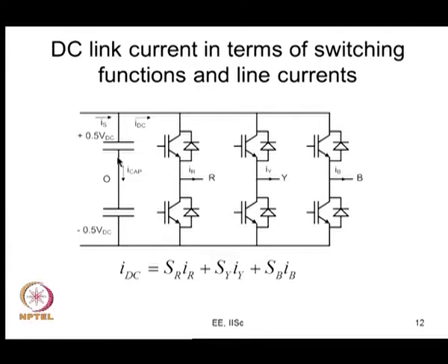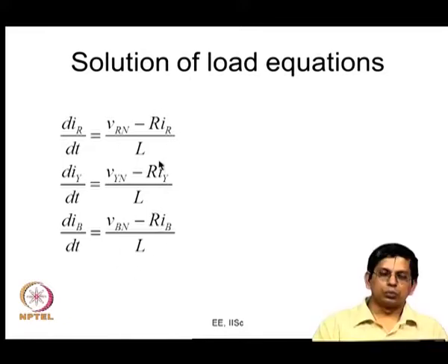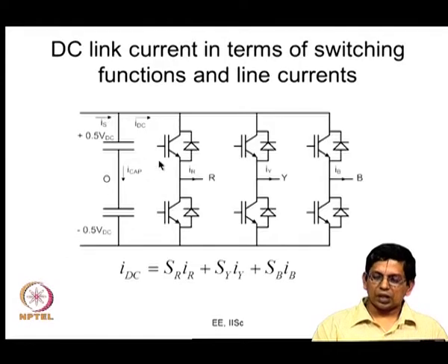So, these IR, IY and IB can now be used. These IR, IY and IB come from the load. The load is not necessarily an RL load, it can also be an induction motor load. In this case these equations can be more complex, but in courses on motor drives you would have studied about modeling of induction motors and so on, and you will know how exactly to simulate from those courses. So, those IR, IY and IB from the load have to come back here. This is what you are using now.